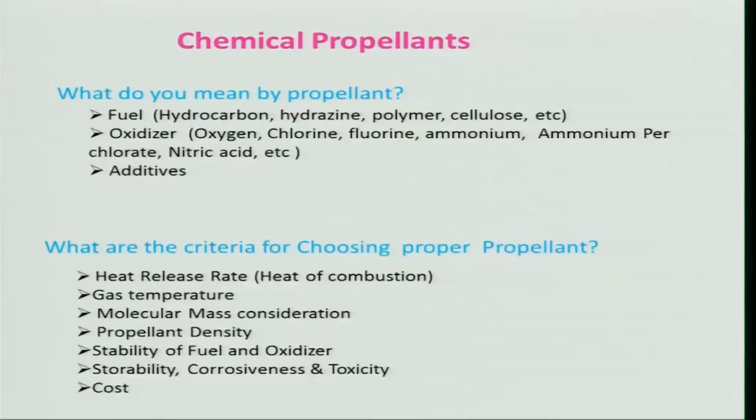And besides this, storability is very important, whether you could store it properly or not, whether leakage is there, or the vapor pressure and other things, one has to look at it. So, corrosiveness and toxicity: suppose there is a leakage, or people will be handling the liquid fuel and other things, particularly if it is toxic, then it is a big problem.